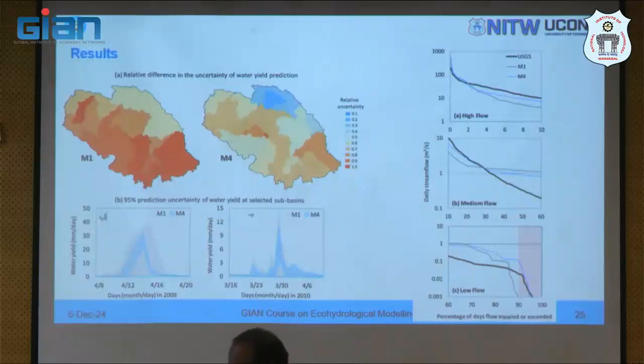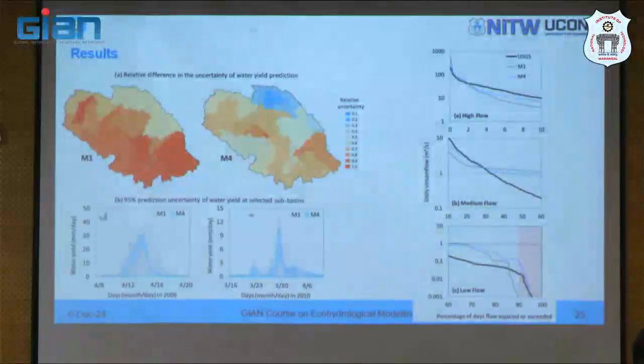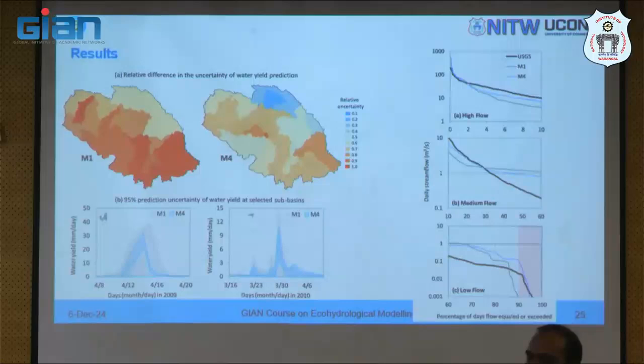Okay. In that approach, you take the similar catchments, estimate the parameters there, and then transfer them to the ungauged location, right. Now, that is the traditional approach, but it also had a lot of uncertainty. So, we wanted to look at, can we reduce that uncertainty by adding the soil moisture data in the parameter estimation approach. What we observed was our uncertainty reduced something like this, but the accuracy was more or less similar, right. We had almost similar accuracy as just using the regionalization technique, right.